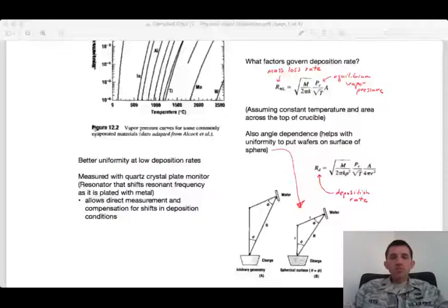But a typical setup for an evaporation process is fairly simple, right? You need a vacuum chamber. It could be as simple as a bell jar like this. You need a charge, that is your metal, to be evaporated, and then you need to heat it to increase the vapor pressure. So you might put it in, say, a resistively heated crucible, something like that. You need to pump it down, right? So we talked about vacuums. From atmosphere, you would start off with a roughing pump, and that would get it down to a certain regime. And then if you wanted to go lower, you would need a different design of vacuum pump. So you might switch over to a diffusion pump. It might have a cold trap.